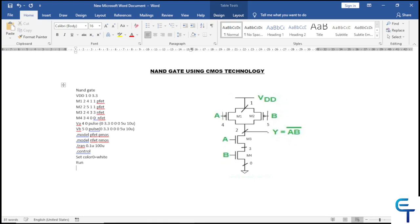To run the code, here we require 3 plots, 2 inputs and 1 output. So input is at node 4. Second input is at node 5. As it will overlap, we'll give a spacing of 5 here. Then output is at node 2. Let's give spacing here as 10. And the control part and the netlist.